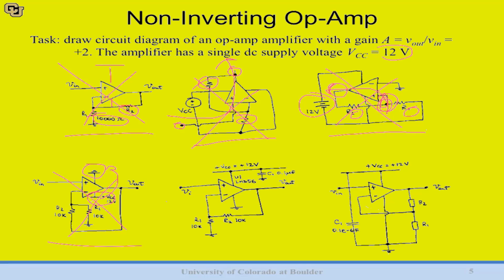Jumping over to lower right, here you can see we've used this rectangular symbol for resistors, and that's fine because we've been consistent with it. But we've managed to draw this circuit with an extra jumper there, so we've had to jump 2 wires over each other, which you actually don't have to do with this schematic. Additionally, when we labeled our capacitor, you can see we label it as 0.1 times 10 to the minus 6. You should have just written 0.1 microfarads. It would have been much clearer. So for those two relatively small reasons, we'll not use that either.